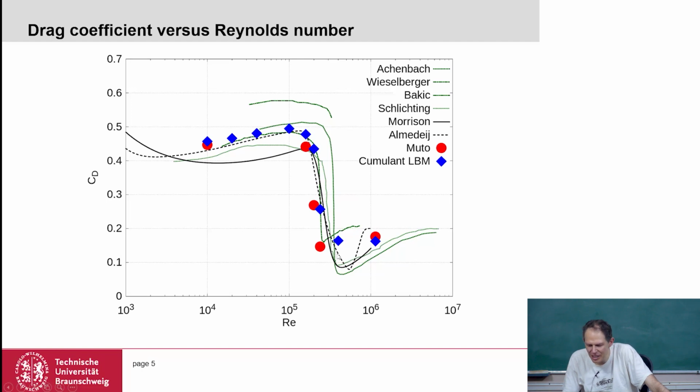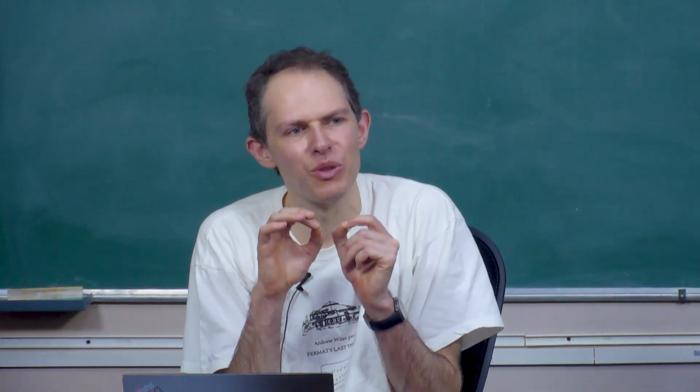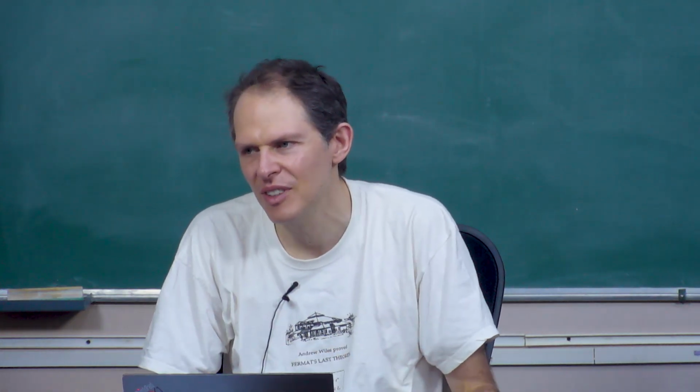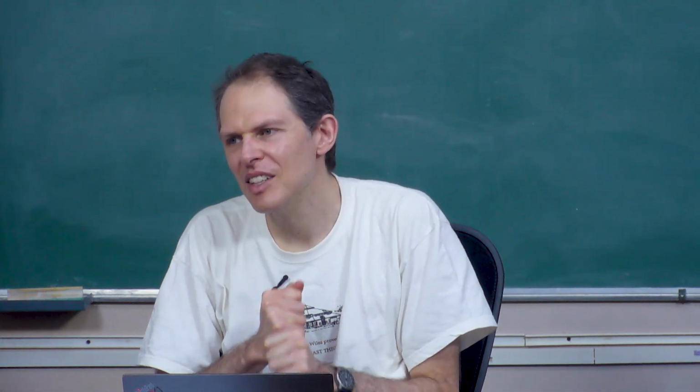This has a very interesting behavior in a sphere, because if you cross a certain Reynolds number, suddenly this drag coefficient drops down by 80%. And the reason for this is in the boundary layer. So you can capture this only if you have the physics of the boundary layer resolved. And in order to do this, your method needs to be stable enough, and it has to be accurate enough. It's easy to make a Lattice-Boltzmann method stable, even for high Reynolds numbers. But what you observe then is that you do not recover this behavior, because the stability destroys your boundary layer.